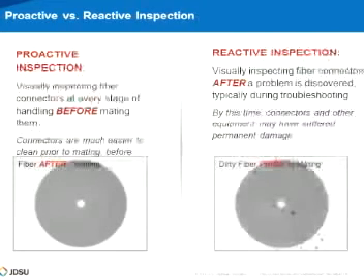After you connect the fiber and there is dirt, imagine it like a rock, while fiber is made out of glass. It's a huge pressure where the 2 connectors are connecting. It will basically create damage on that interface.